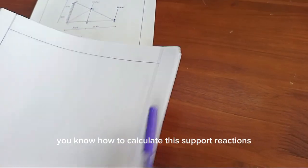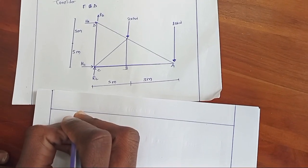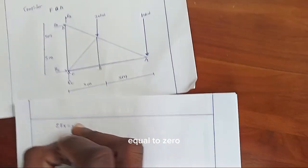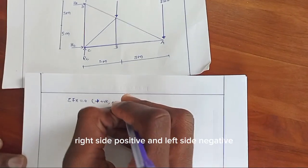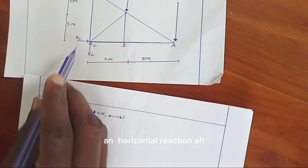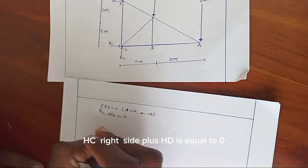Now, in order to obtain these support reactions, we consider the equilibrium of horizontal reactions, which is equal to 0. Right positive and left side negative. Now, horizontal reaction HC, right side plus HD is equal to 0.